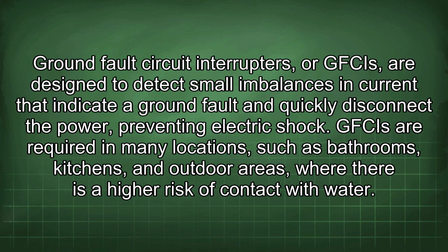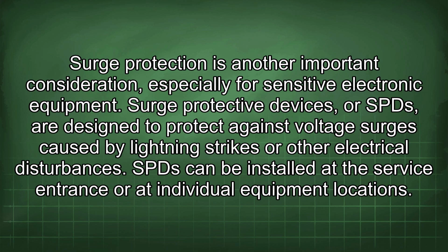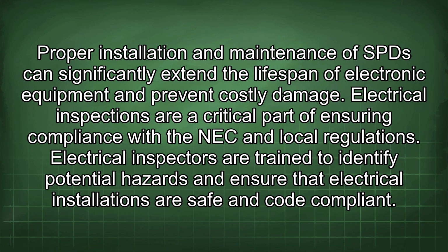Surge protection is another important consideration, especially for sensitive electronic equipment. Surge protective devices, or SPDs, are designed to protect against voltage surges caused by lightning strikes or other electrical disturbances. SPDs can be installed at the service entrance or at individual equipment locations. Proper installation and maintenance of SPDs can significantly extend the lifespan of electronic equipment and prevent costly damage.